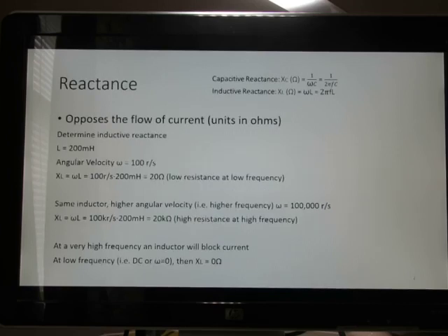So we're in chapter 20. Any changing current in an inductor will be impeded. The current will be impeded as a result of the inductance associated with it. Inductive reactance in ohms is proportional to frequency. And I gave a couple examples right here of an inductor in a circuit with a change in frequency, and we should know how to